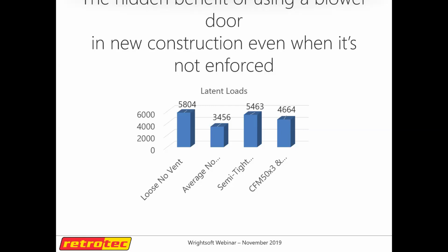What you're going to find is if you use the Manual J ballpark values for tightness, right? You say, okay, this is new construction and I'm in this climate zone, and it roughly works out that that's pretty similar to what the code says. So I'm going to use semi-tight, and then I employ the ASHRAE 62 rules for designing the ventilation system. I don't get to take that outside air as an offset when determining how much ventilation I need to design for. The theory behind that is if the minimum standard is this much, you can't just say it's going to be the minimum standard.